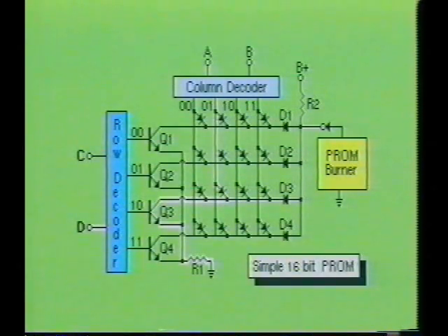First, an address is selected by activating the desired row and column lines. Then a jolt of high energy is applied at the desired address. This causes the thin layer of conducting material to burn open. When this occurs, it permanently opens the circuit between the row lines and the column lines. This same procedure is performed at each data address until the entire PROM device has been programmed. While the device is being programmed, the outputs are generally disabled.